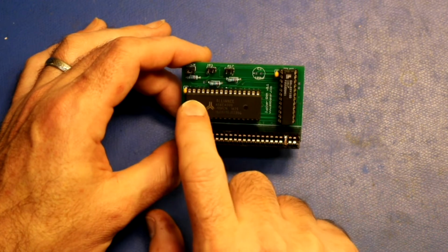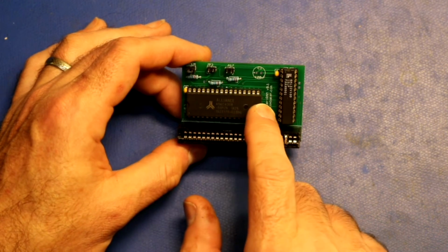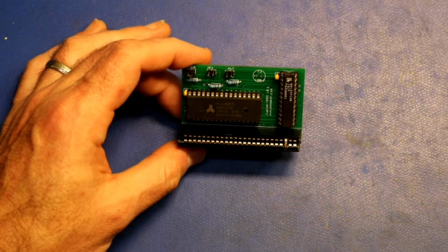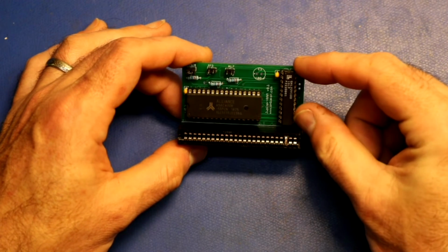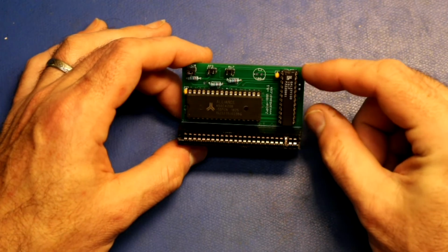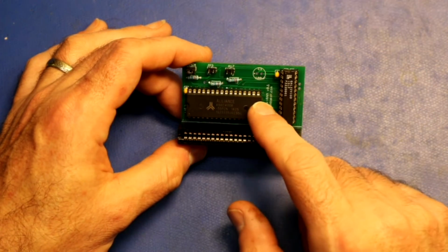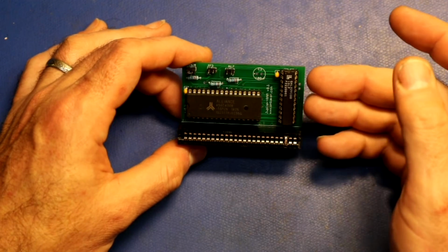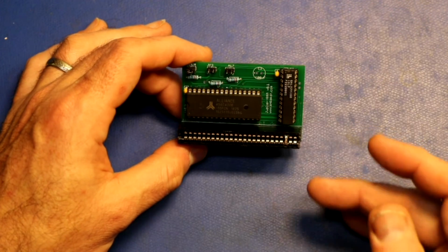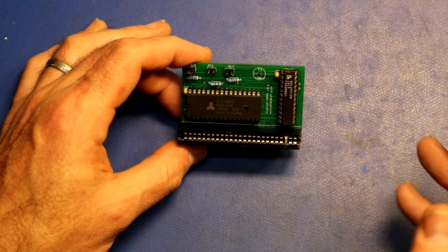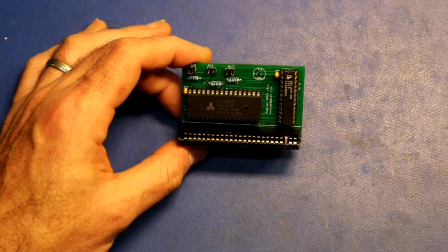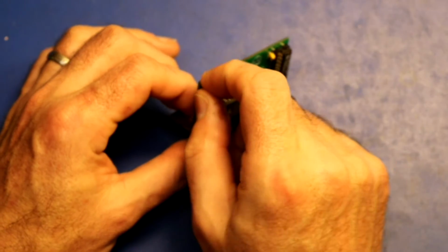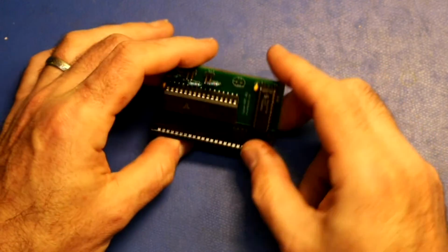So this is actually quite a large RAM chip. We only need 48K of it. But you can implement various paging schemes. So inside of my PLD, I actually have room, if I want to, I could page that 48K in 4 pages by using a couple of data bits attached to a port. I haven't actually done the paging yet because I see absolutely no need to have more than 48K of RAM. So right now I'm just using this as a straight RAM board. The jumper up here is an enable or disable for the RAM board.